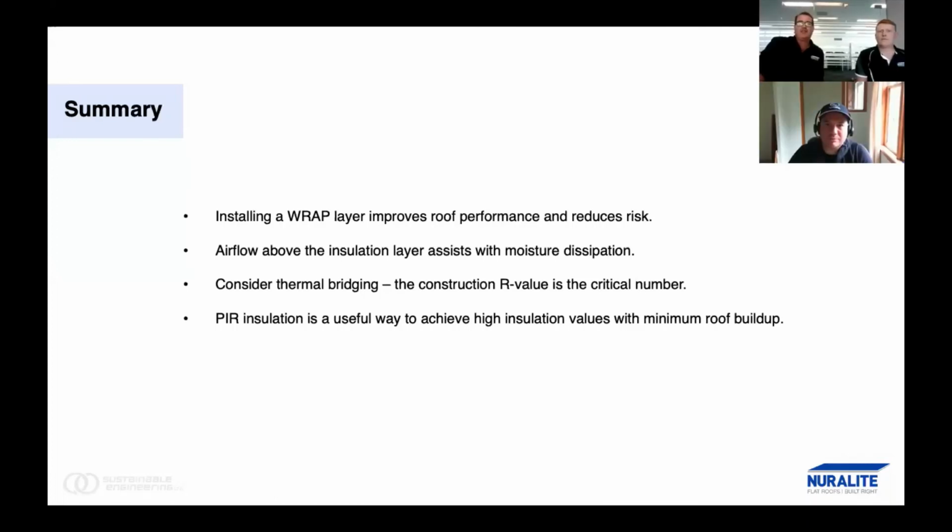Got a question here for you, I think, Peter. Someone's asking, is the flat membrane warm roof trafficable? Is it walkable? It's okay for light maintenance traffic. If you're walking on it every day, then it's not acceptable for that. You'd have to put a floating deck on it.